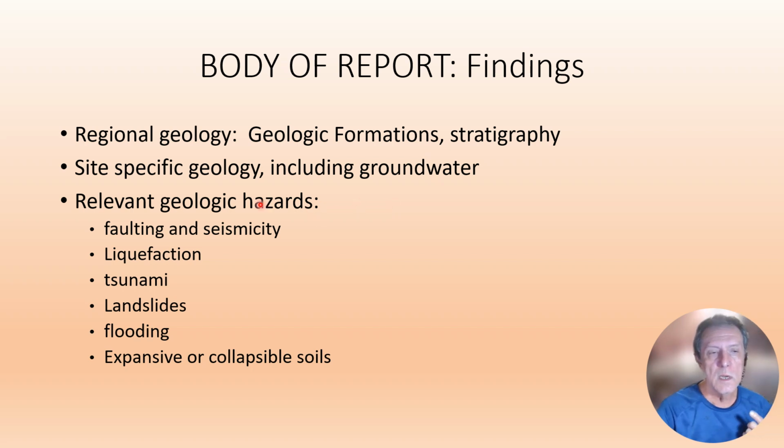Body of the report is going to discuss relevant geologic hazards, faulting and seismicity, presence of liquefiable sediments at certain depths, the vulnerability of your project to tsunami. Is it near the coast? There are maps available by California Geological Survey that show tsunami hazard zones, for example.